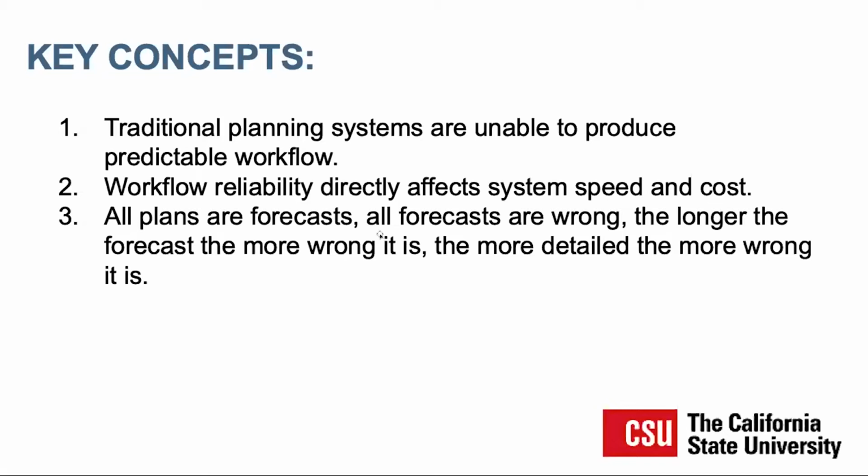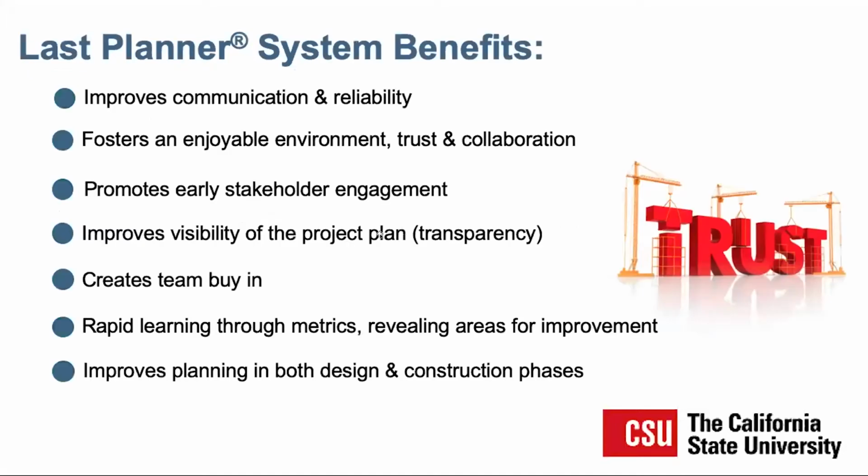So we routinely see projects where they'll have 2,000 or 10,000 activities with an extremely finite level of detail. For instance, on August 13th of 2022, we're going to be doing finished electrical trim out in rooms 901, 902, and 903. The likelihood of that happening is infinitesimally small. And so why do we plan that level of detail too far in advance? Well, we shouldn't. And so there's an appropriate way to do that. And that's what Last Planner really helps us do.